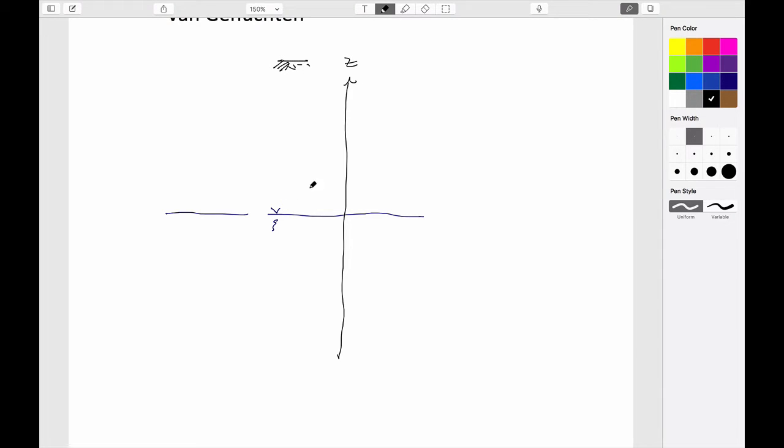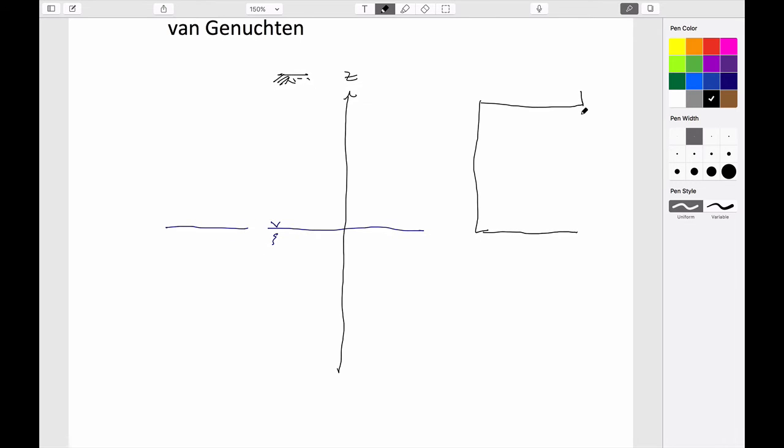And if we draw a capillary pressure versus saturation curve above this, then we know exactly what that should look like, I think. We know that capillary pressure is equal to the pressure of the non-wetting fluid minus the wetting fluid, by definition. And this is capillary pressure that we're plotting on the vertical scale. So this is PC. And it actually relates to the assignment you're doing now, I think.